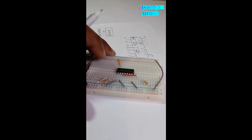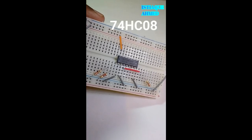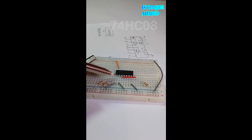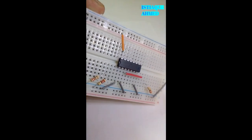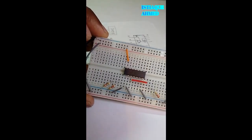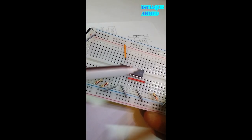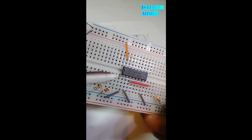Here is the breadboard, and we put the 74HC08 AND gate IC. This is pin 1 and this is pin 7. You can see the round circle here, which is close to pin 1.